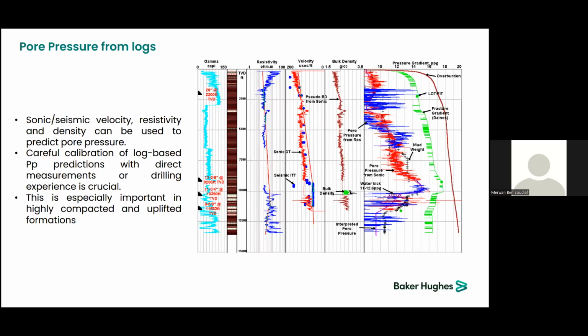And this is how we are constructing a pore pressure profile that also needs to be calibrated or verified against the drilling experience, and whenever it's possible against direct measurements such as DST or MDT, as I mentioned before.